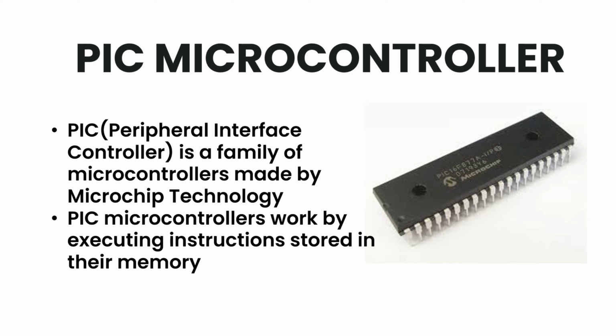The CPU executes instructions using fetch, decode, and execute, as we earlier discussed, ensuring continuous operation as long as power is supplied. They use the reduced instruction set computer, that is RISC architecture, which allows faster execution and simpler instruction decoding compared to complex instruction sets. Most instructions execute in a single clock cycle, making the system efficient and predictable for real-time applications.